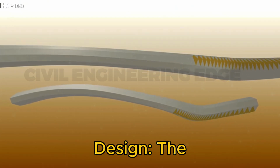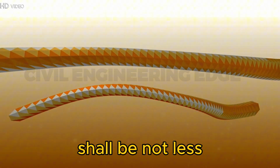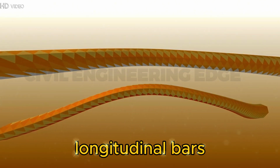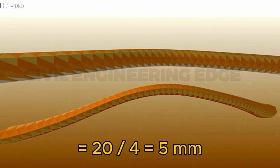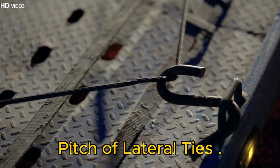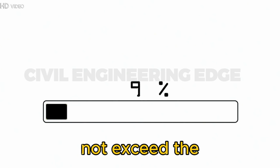The diameter of the lateral ties shall be not less than 1/4 the diameter of the longitudinal bars, equals 20 by 4 equals 5 millimeters. Provide 6 millimeters phi ties. Pitch of lateral ties. The pitch of lateral ties shall not exceed the following.